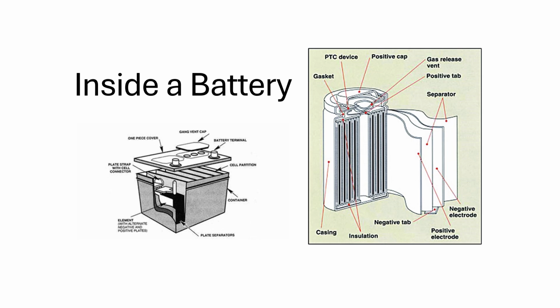This here is the inside of a battery, so you can kind of understand what batteries are. They are not all like this anymore, but some of them still are. They have the lead acid there on the left. Those are lead partitions, and the liquid is usually sulfuric acid. If you have to refill those batteries, use all safety equipment: the goggles, the gloves, the face shield, and the apron.